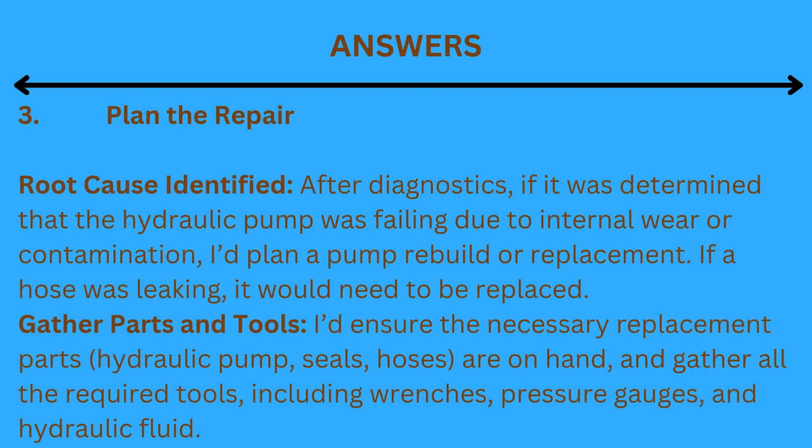3. Plan the repair. Root cause identified. After diagnostics, if it was determined that the hydraulic pump was failing due to internal wear or contamination, I'd plan a pump rebuild or replacement. If a hose was leaking, it would need to be replaced.